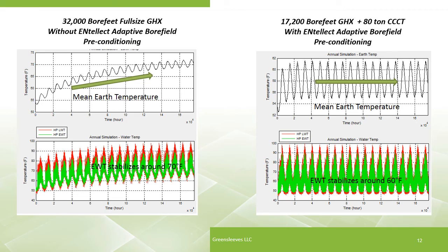Note that the full-size bore field without any preconditioning controls has a rise in the mean earth temperature that stabilizes over time. This is nominally a 20-year simulation. Also notice that the entering water temperature stabilizes around 70 degrees with that full-size solution of 32,000 bore feet.